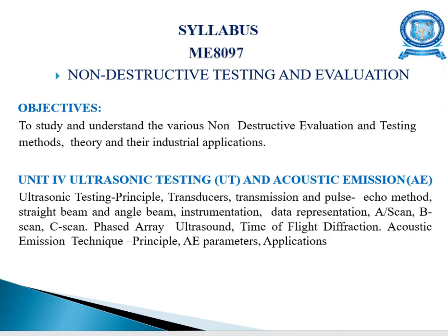In ultrasonic testing, we'll be studying the principles, the types of transducers, the transmission and pulse echo methods, the straight beam and angle beam instrumentation, data representation, A scan, B scan, C scan, phased array ultrasound, time of flight diffraction, acoustic emission techniques, its principles, acoustic emission parameters, and the industrial applications of ultrasonic testing.